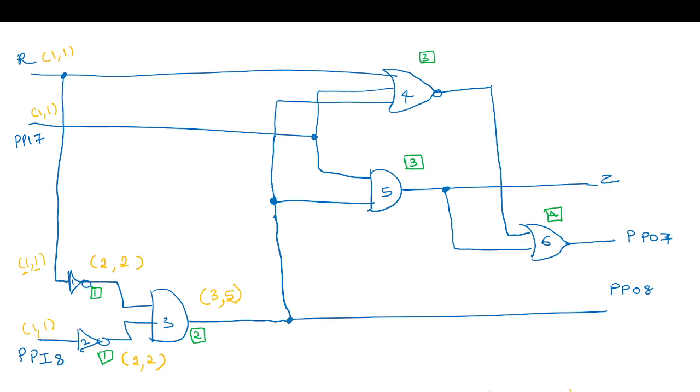This example is taken from the Essentials of Electronic Testing book. And this is important because we initially didn't mention any metric. We said that if we have two paths, say this is one path and this is one path, and I want a 0 here, I have a minimum effort of 3 if I set any one to 1.